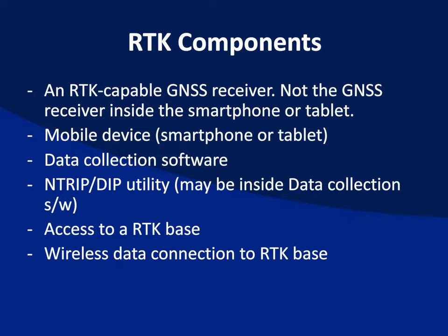Okay, so there's RTK networks out there. There's single base RTK bases. You need some piece of utility software to manage the connection. You have the IP address, the port number, password, login. You need some kind of software utility to manage that connection. Some manufacturers of data collection software build that utility inside their software, but most of them don't. But there are third-party pieces of software you can use to enable you to use apps that don't have that capability built inside.